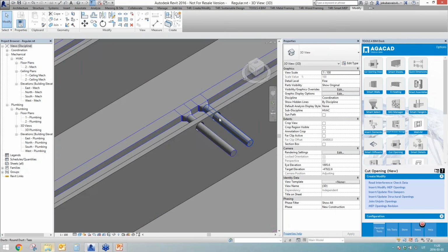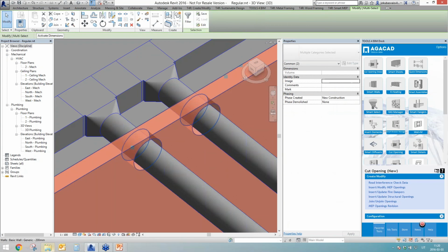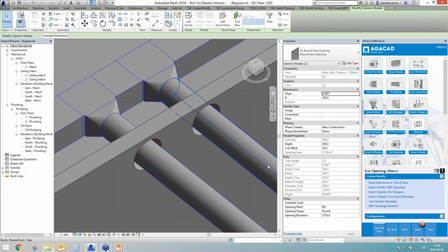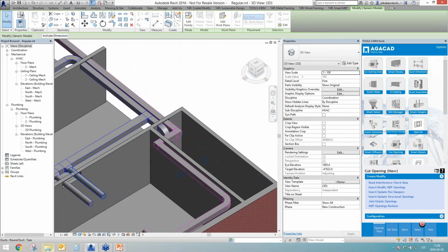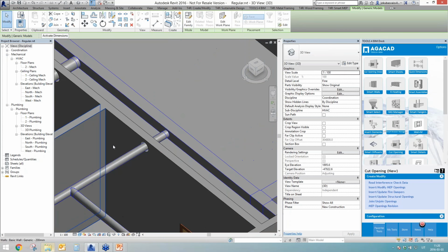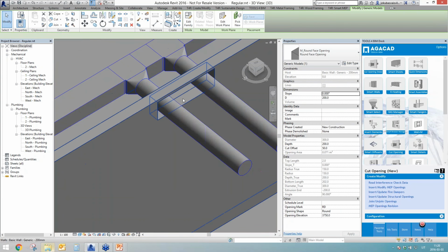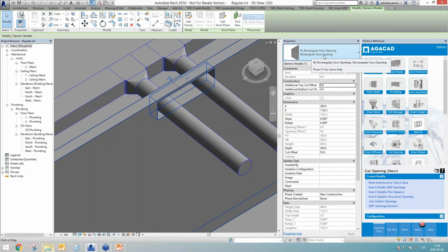Let's move to the 3D view. I have two openings and I want to auto join them. So I'm clicking on one, on the second. Okay, I will take them like this, one and second. And I'm using join and join openings. And the opening right now is bigger, like it is joined. It changed the family. Before we had something like the round opening family, and we changed the family to the rectangular one. So I have a rectangular face opening.